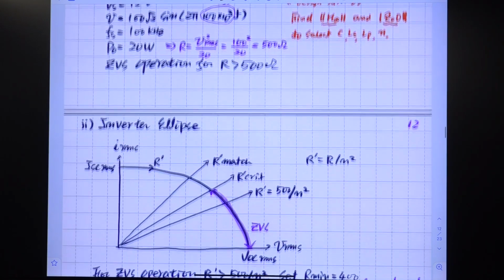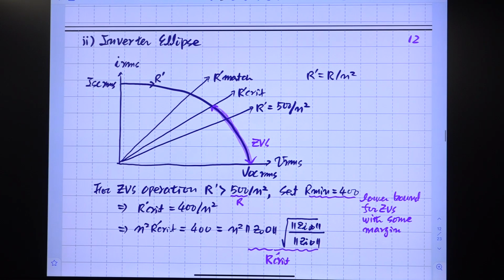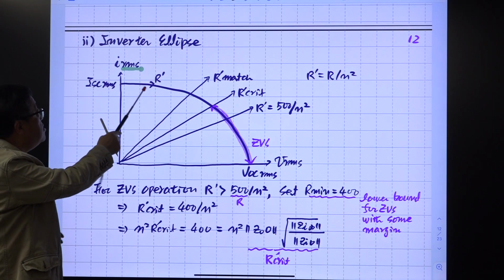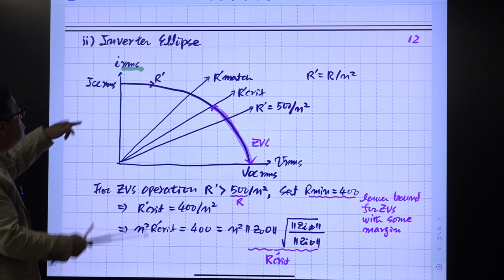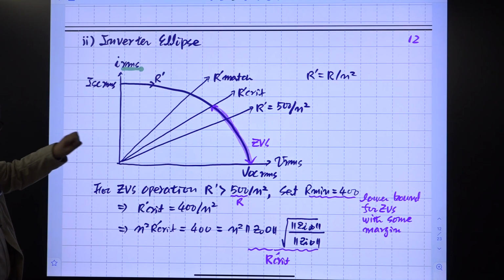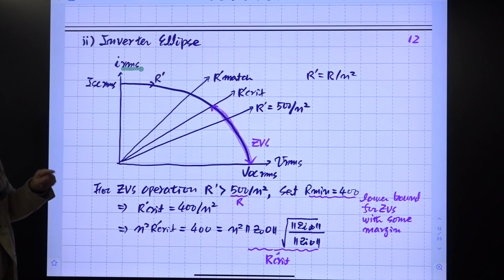All right. So inverter, I'm using this notation. Previously it was I magnitude, but now I'm using this I RMS. It really doesn't matter if I use RMS. Everything should be the RMS. So you don't have to use magnitude always. For this design purpose, it is much better to use RMS value. This RMS is directly related with output power, so on. So you don't have to play with 1 over square root 2 anymore here.